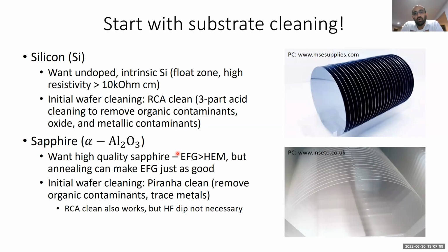You want your substrate to be insulating, ideally, and that will lead to lower dielectric loss, especially in the cryogenic regime.